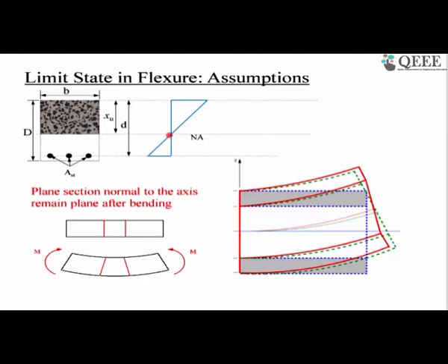Okay. So this is the neutral axis where your strain is 0, this is the compressive strain at the topmost concrete fiber, and this is the tensile strain at the center of the reinforcement. So this depth is the effective depth. After this, whatever calculation we make is in terms of effective depth. When we say the depth, implicitly I mean it is the effective depth only.